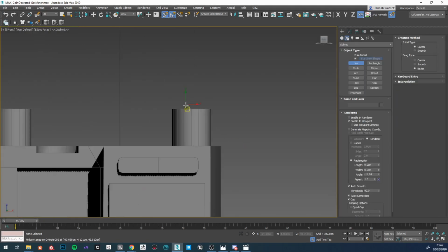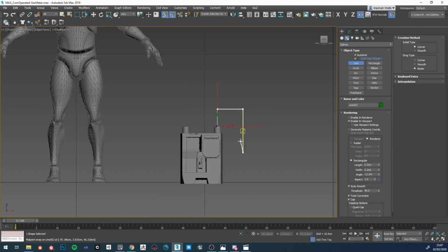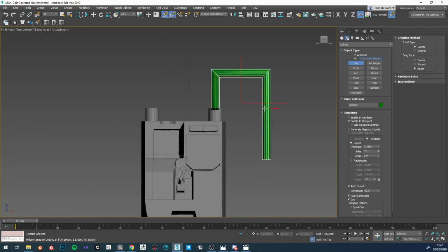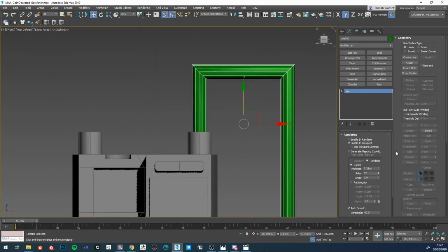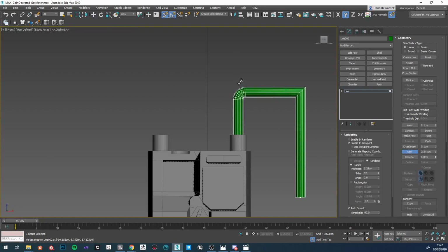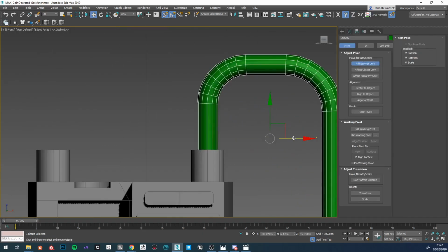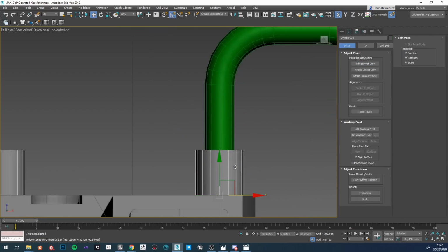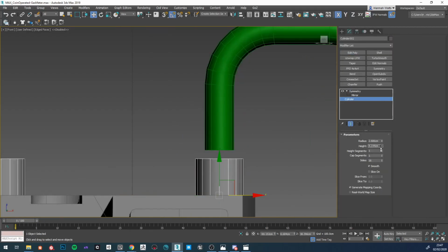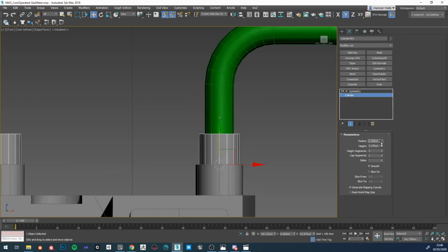With the front bit worked out, I will quickly block in the pipes with splines. For easiness sake, I draw out the overall shape with right angles, not bothering to introduce any Bezier curves, and then I use the fillet tool to curve those hard corners. I'll also refine the blockouts of these pipe connectors a bit to better represent the layers of nuts and bolts that we're going to need to make.